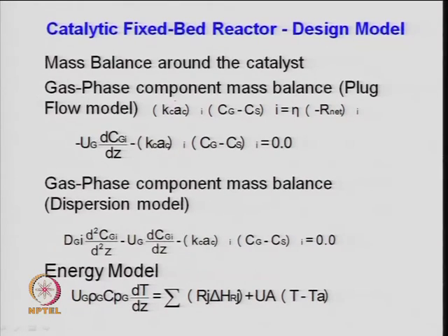Same thing, energy balance means energy input minus output minus disappearance because of chemical reaction, and that is again at steady state 0, right. So, these steps have been discussed. The first thing I told you is K_C times C_A at the interface, that is C_g, the concentration in the gas phase, minus the concentration at the surface of the solid.